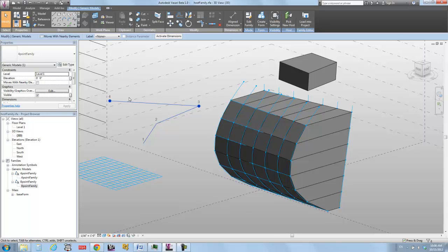So we're doing a couple different things here by having loaded families. Here we've got a one-off shape of the exterior form of the building, and we're separating it out largely for performance reasons. That is, I can manipulate it somewhere else and then load it and then have all of the rest of the regeneration happen. There's also some clarity in saying, okay, this is going to be the form file, and somebody else on my team is going to be working on the form while I work on the components. So there's also the ability to parcel out the work to different people.